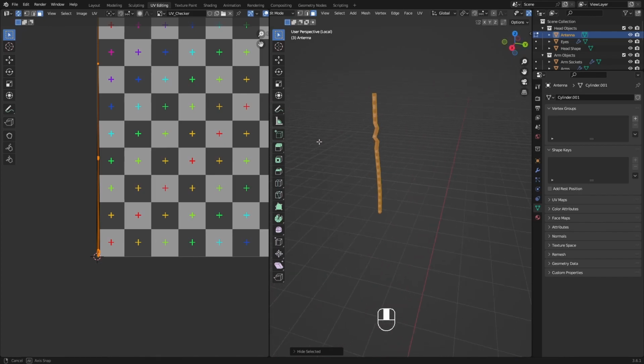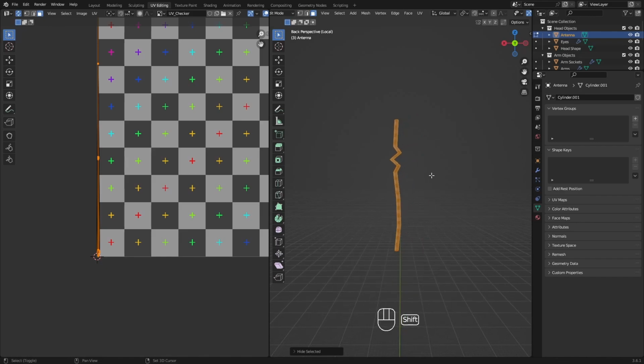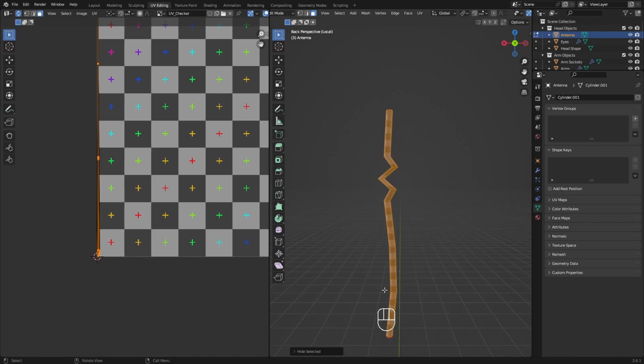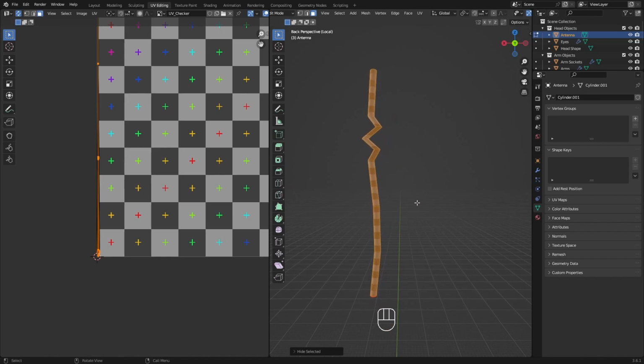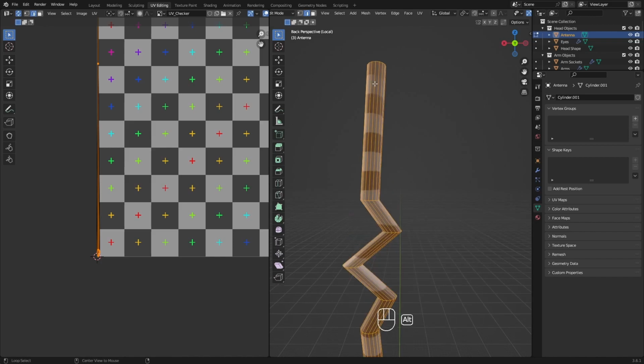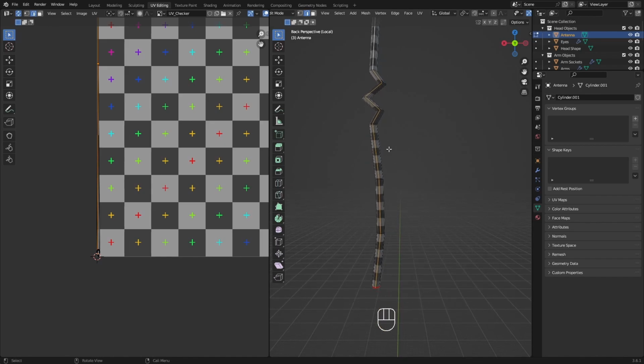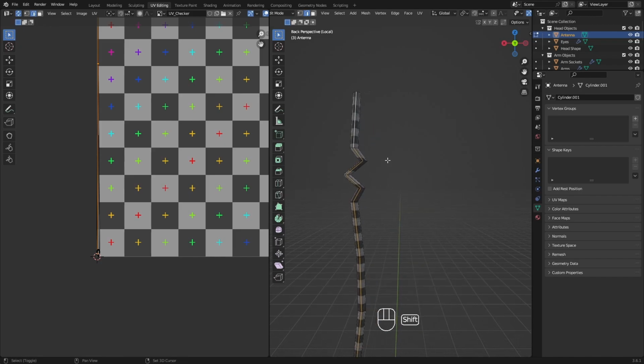All right. Now what I'm going to do is again go to the back. So back perspective, we can click this guy here as well. So for example, I'm going to click on this, and then I'm going to the back, and then I'm going to open it just like we did with the eye and the base of the antenna. And here, the same thing, I'm going to press Alt and click, and it's going to select all the edges that go along this path. So now that I have it, I'm going to press Q and then mark seams.